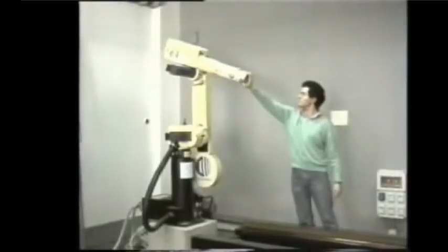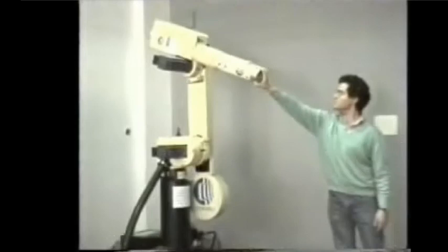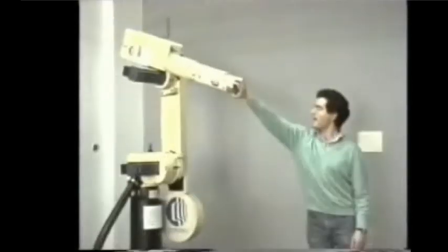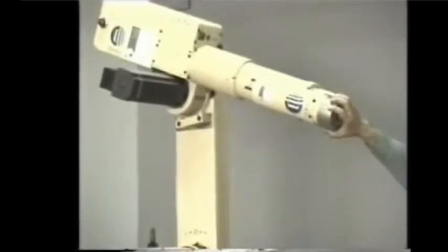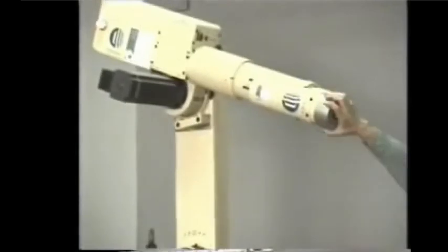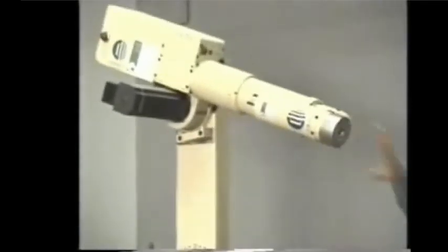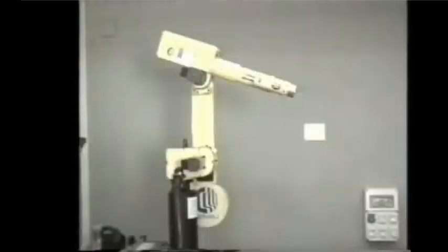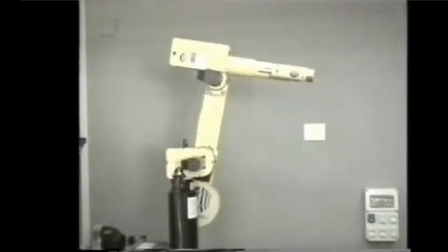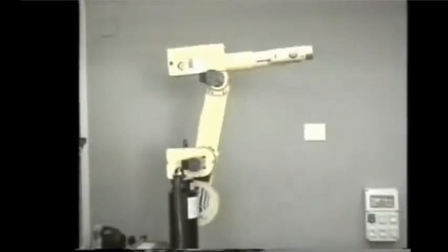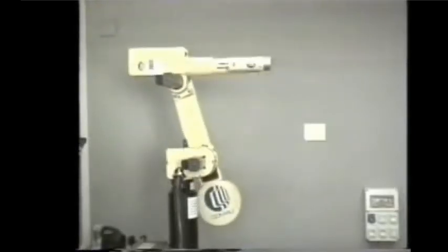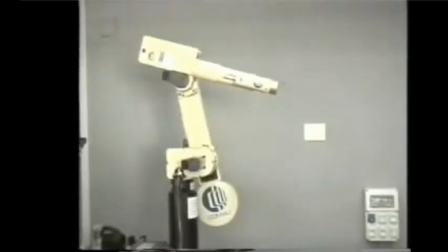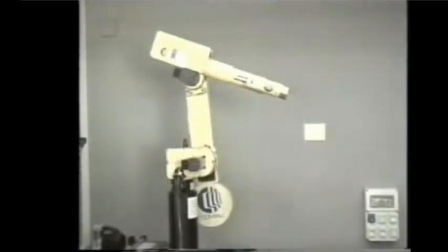Now, if you reduce the proportional gain, the robot will behave in a more compliant way, so it will accommodate and then return to the same initial position when you're pushing or pulling. And this can be made six-dimensional in a sense. Now, if with the same low gain you try to trace the same circular path as before with the same speed, you can immediately realize that you're not really drawing a circle. You can tell it from this video,